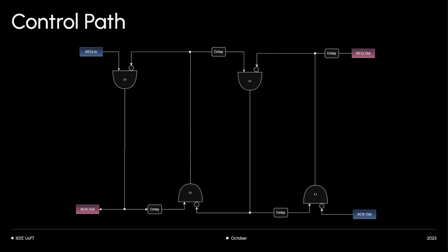And that's what is asynchronous over here. In the case of synchronous logic, my clock cycle for this big fat logic here affected stage 1, stage 3 as well, like stage 0 and stage 2, not just stage 1. You get what I'm saying? The effects on one side in asynchronous logic really don't get through to the other side, and that's its power. Does it make sense? Is it clear? Okay, let's move on.